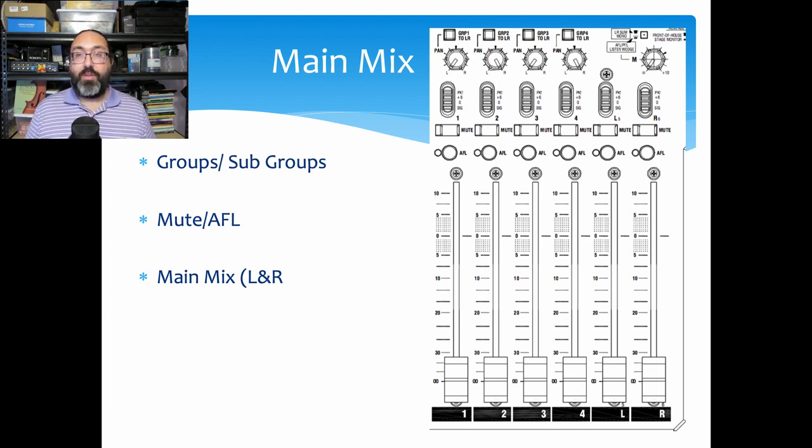I have had some systems that were set especially hot that I had to back down off of, and I didn't have time to actually do the proper gain adjustments down the line to turn the amplifiers down. But most of the time, you will have this at unity, which is that 0 mark. And this is also good. So if you ever have an engineer come behind you, you want to set that to this unity mark.